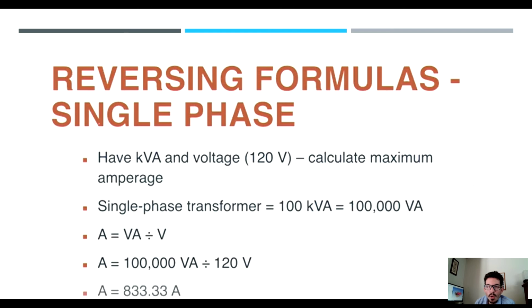See what's the voltage going into the system by the transformer, or if it's plugged into a regular wall socket, or the plant will have drawings about the voltage going into the systems. So you use that voltage. If it's single phase, you know that you don't need to use the square root of 3 at all.